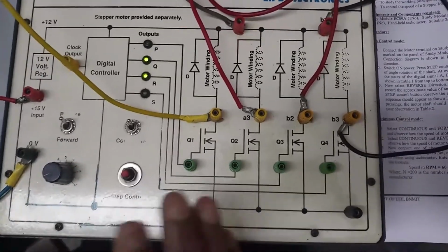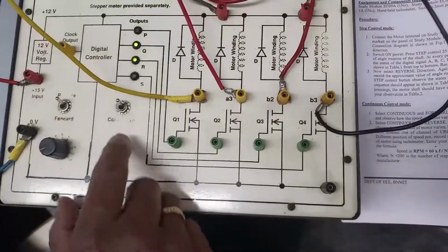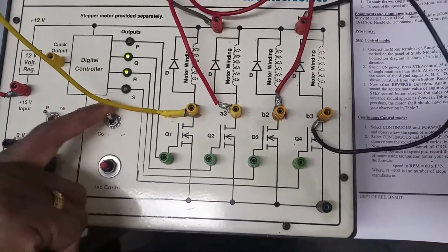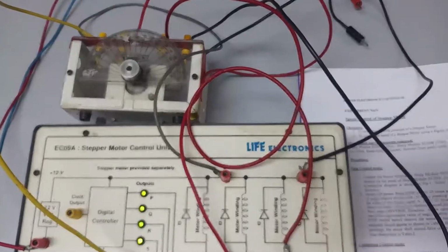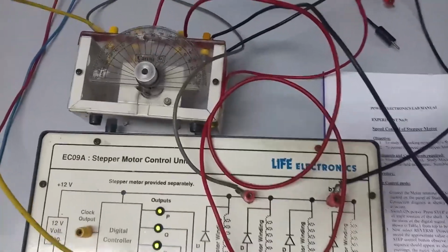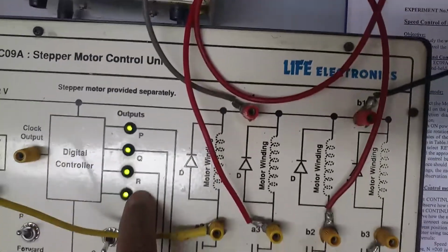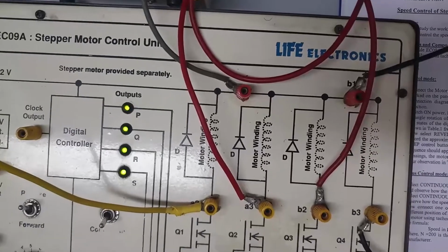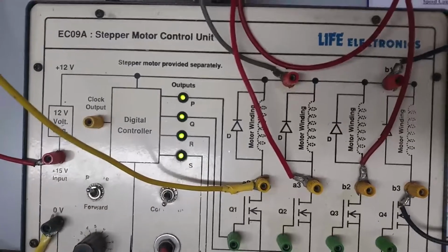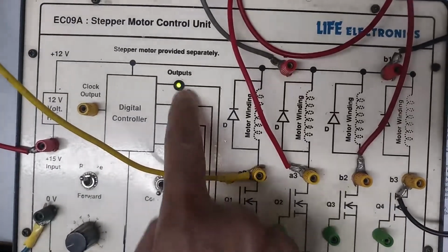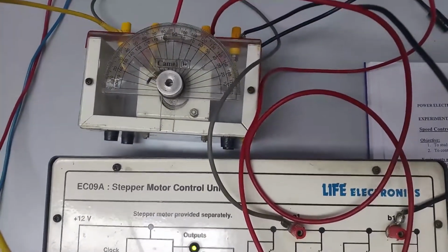Now this is a mode 1 operation where we go for a step mode. Then we go for a continuous mode. In case of continuous mode, move this toggle switch from the step mode to continuous mode. You can see the motor is rotating continuously, and we are generating the pulses at a higher frequency. You can see here all are glowing green, which means that all are giving pulses one after the other. Since all of them are giving the pulses at very high frequency, we feel that all of them are glowing, but actually the sequence 5 6 10 9 is continuously coming to all the switches.